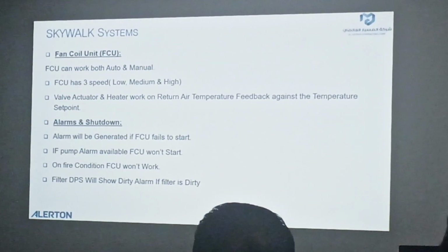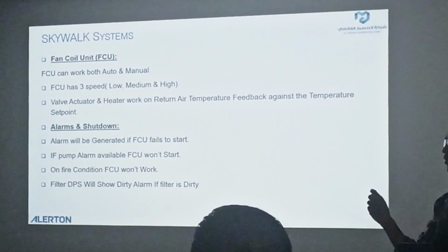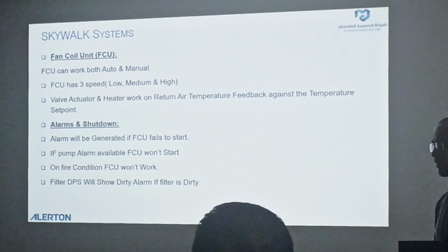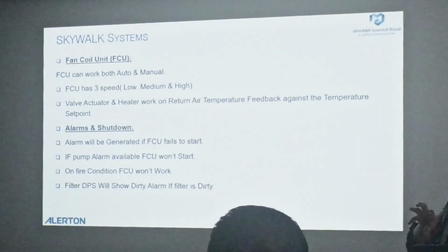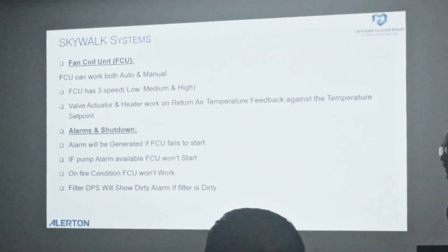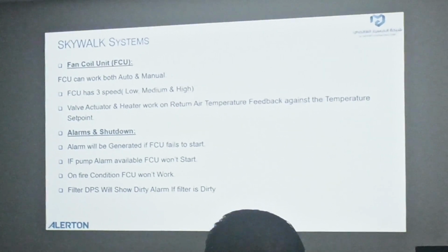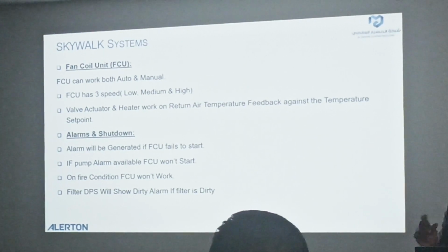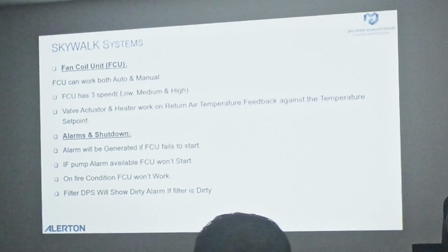I think how much pressure difference do we adjust? 100 to 200 pascals. It is variable. The DPS itself is available there. You can adjust it, 100 to 200 you can adjust. There is a knob available so you can adjust.